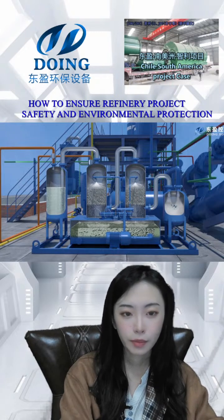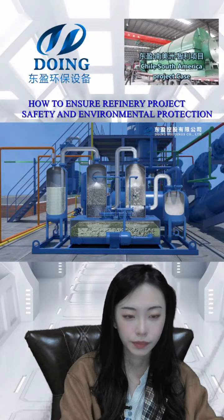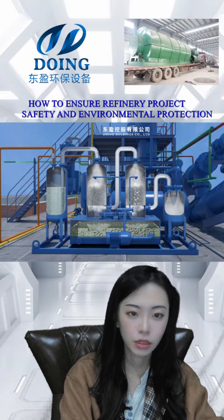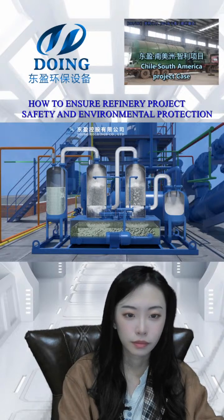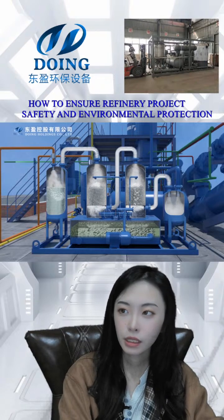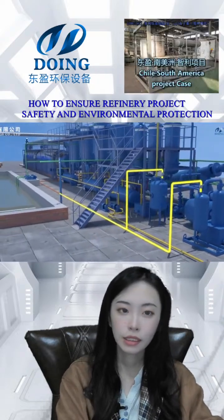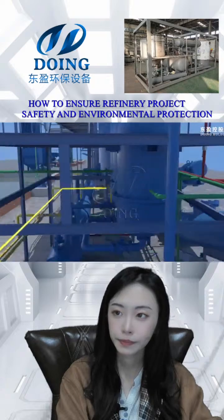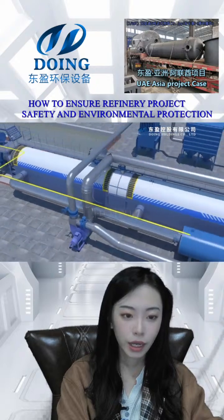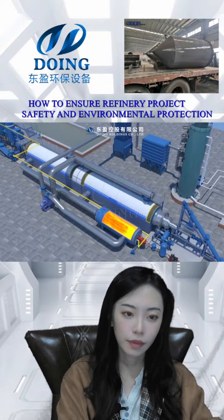You can see first is a buffer tank to slow down the speed. And then this is a spraying tower to spray recycling water with the sodium hydroxide. And the last one is the water seal, also the same effect to prevent the tail gas flowing backwards. And then by using this tube, the tail gas will come to the hot wind burner, to burn it to save our extra heating energy.